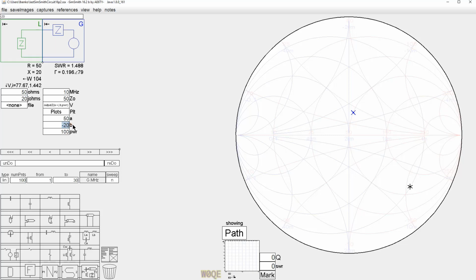Of course, if this is minus, say, 50 ohms, and this is plus 50 ohms here, then the difference is, I believe, 25. Yeah, it's 25% in power. But it lets you, again, it produces 1 watt into the impedance that is Z naught, with this output impedance, 50 minus J50 in this case. So it's a lesser used generator by far. I don't think I've ever used it for anything particular other than just to mess around.